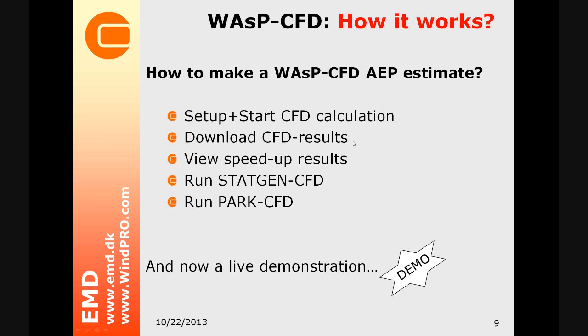I'm going to show how the download of the CFD results is done, how you can view the speedups on the map, how to run a StatGen to generate a wind atlas or wind statistics, and then run a wake loss or park calculation within WindPRO by using the standard N.O. Jensen wake model and also the CFD results. So now I'll do the live demonstration.